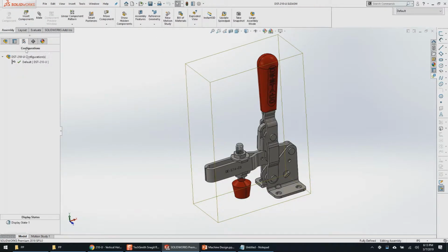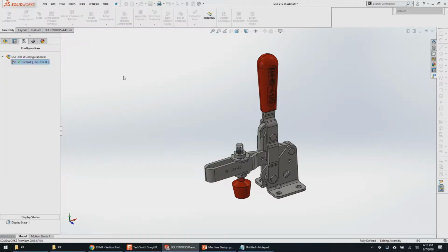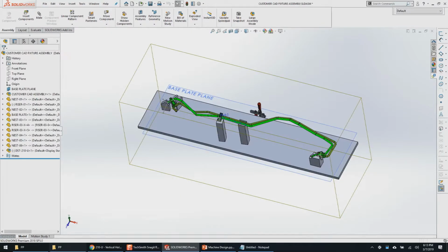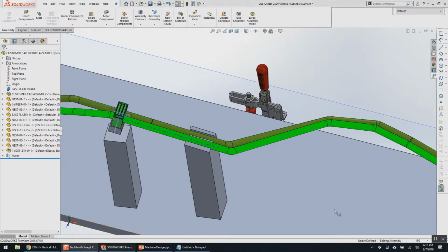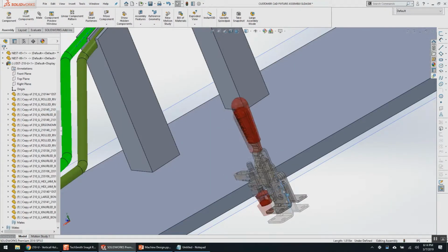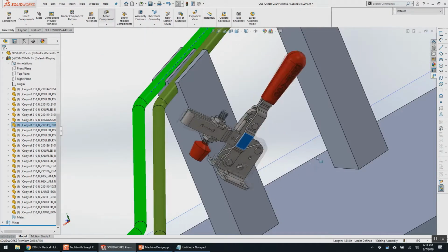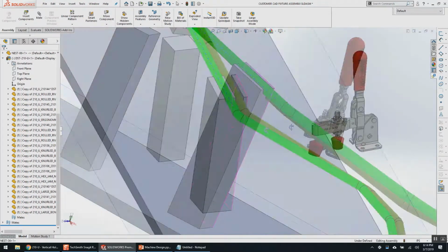So going back to the design now, let's insert this Destaco clamp, which I should quickly, while I'm thinking about it, make sure that those child parts are hidden so that SOLIDWORKS recognizes this as a part file, not as an assembly file. Close out some of these folders. For some reason that didn't work last presentation.